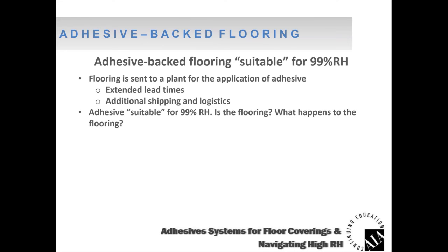If the adhesive is suitable for 99, ask the question, is the flooring suitable for 99? Ask the manufacturer. Okay. The adhesive is unaffected at 99. Is the floor covering unaffected? Okay. Look at the pH restrictions.